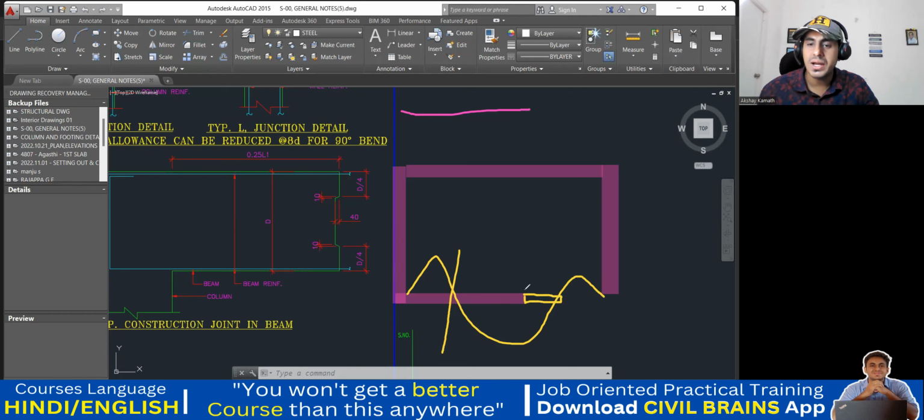This much portion at any cost you do, so that you're stopping at the point of contraflexion. So tomorrow when you come, you start your concreting from here. Not an issue, because here your bending moment is very less. Nothing will happen. That is the first concept.